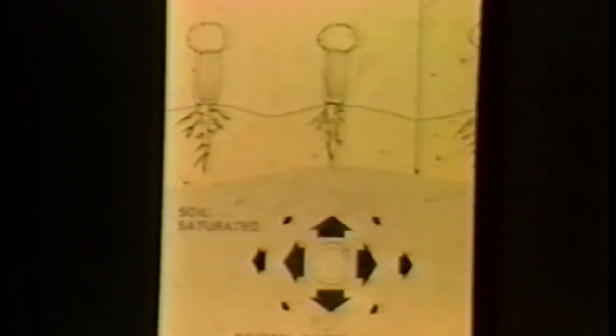Below surface irrigation is classified into 2 types: sub-irrigation and subsurface irrigation. With the sub-irrigation method, water is supplied to the root zone by artificially regulating the groundwater table elevation. In sub-irrigation, check dams and gates are used to maintain the water level in the soil from open ditches, or water is supplied through jointed or perforated pipe.